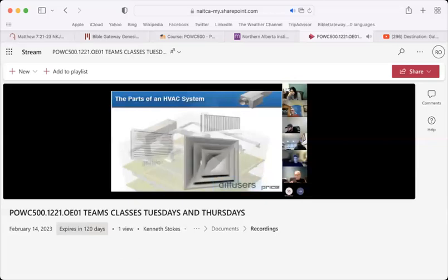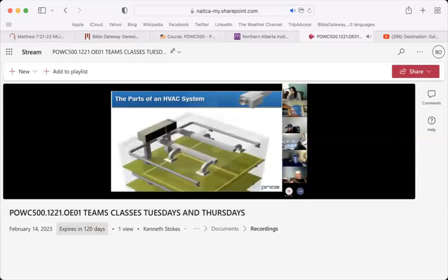A diffuser is an air outlet which incorporates structures such as vanes, louvers, perforations, and other features for distributing and directing air. The diffuser's job is to direct the airflow throughout the occupied space in the most efficient manner possible. More information on desirable air patterns is provided in the space air diffusion section. We will discuss diffusers in more detail in air outlet selection.